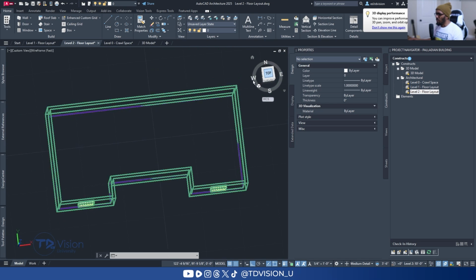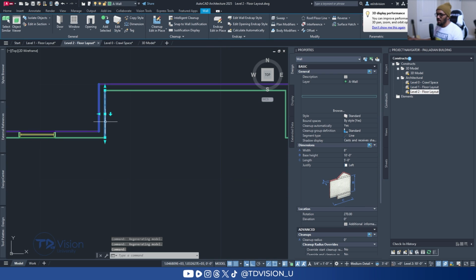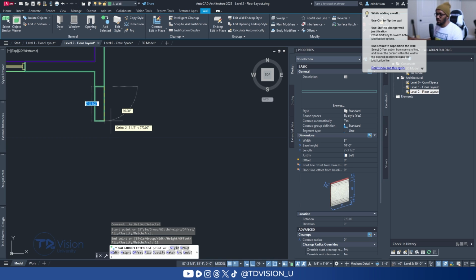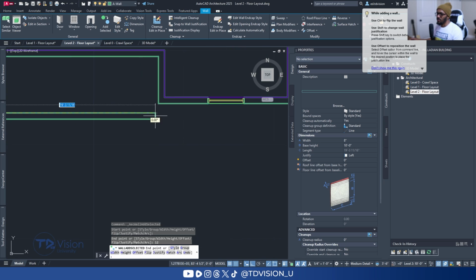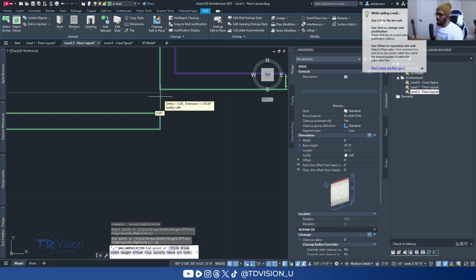I'm not even sure how far out we're going to bring this, but let's try something. I'm going to click on one of these walls, select add selected, and then continue this portion out 1 foot, so 12 inches. I'm going to come across like this, and track this point down and then connect it back there.